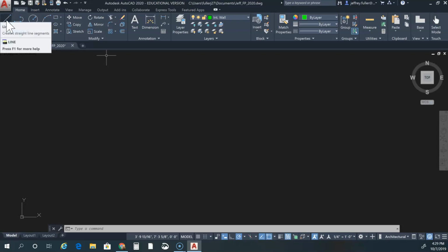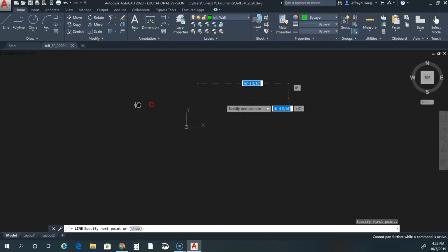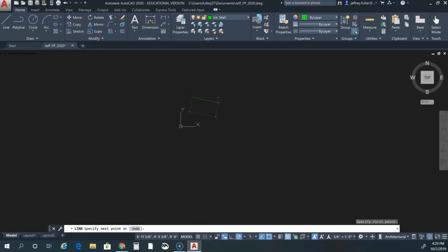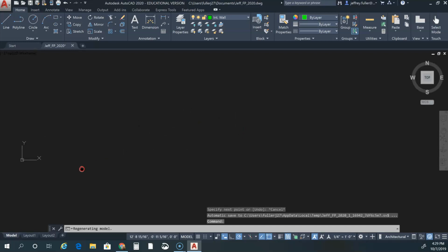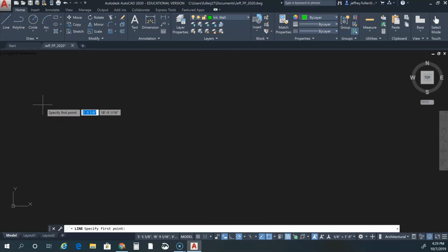We're going to start with this regular line tool. Okay. And the line tool allows me to just draw lines. Right now I'm on the interior wall layer, but we're going to change that in just a moment. So you can just draw it out at whatever layer you're currently on is perfectly fine. And looks like navigating here is a little bit trickier than it used to be. Okay, let me try that again. Okay, so the back of my house, I don't know, it's going to be like 40 feet or so.